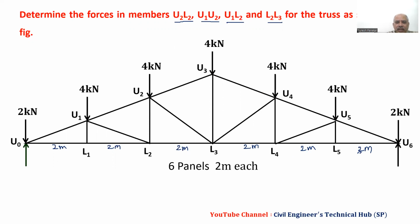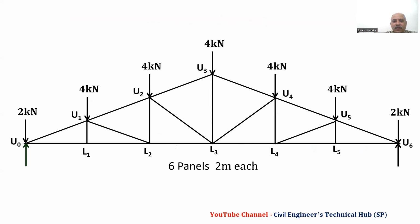Now we will consider the first section, which will cut these three members. That is your choice. I have considered it like this, but you can consider a vertical section which will cut these three members. To cut these three members, we go with a section like this. Generally, the minimum number of members should be cut by the section, and the member in which force is required should be cut by it. So now we will go with this.